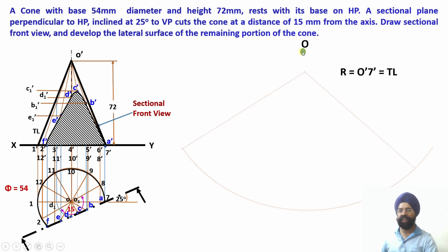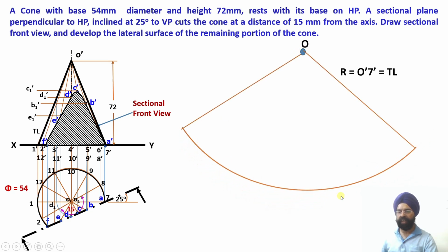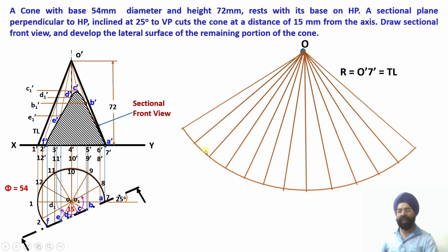So having obtained this apex point, now the curve has been drawn and 12 equal sectors have been obtained. You see, once again this is an approximate method because we are not able to measure the arc length, rather we are able to measure the chord length. Since the shortest distance between 2 points, 1 and 2, has been measured, it becomes a little bit of an approximate method.